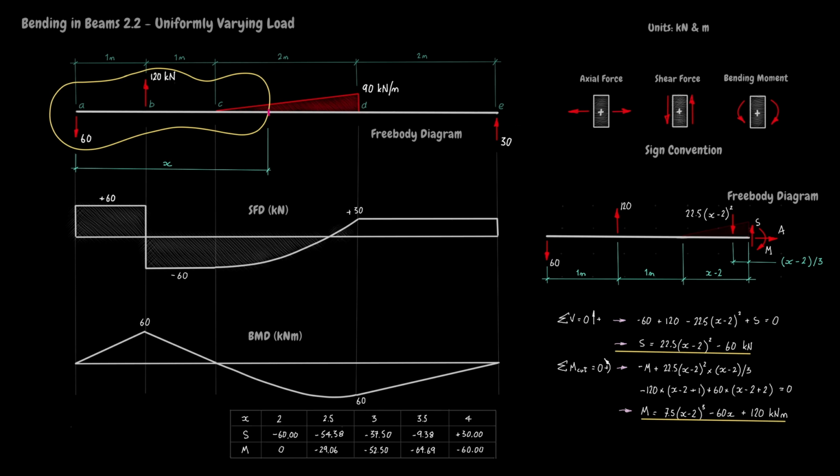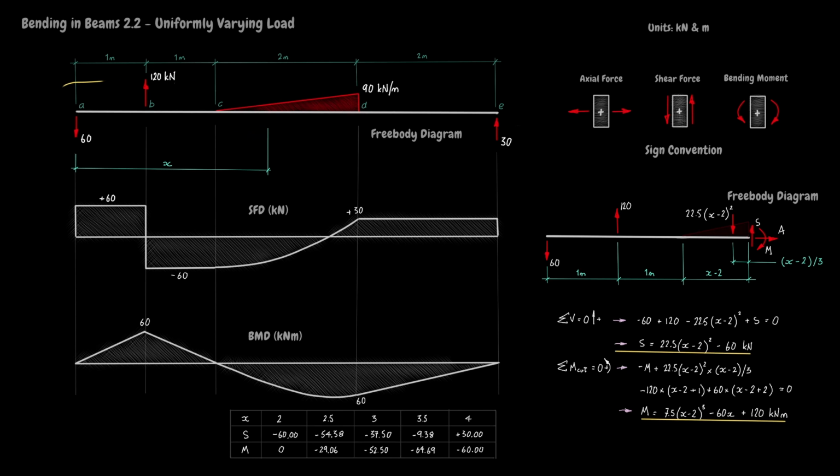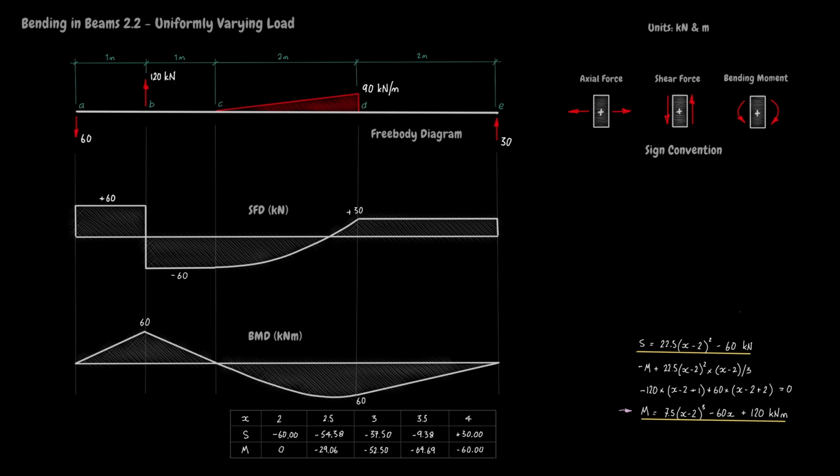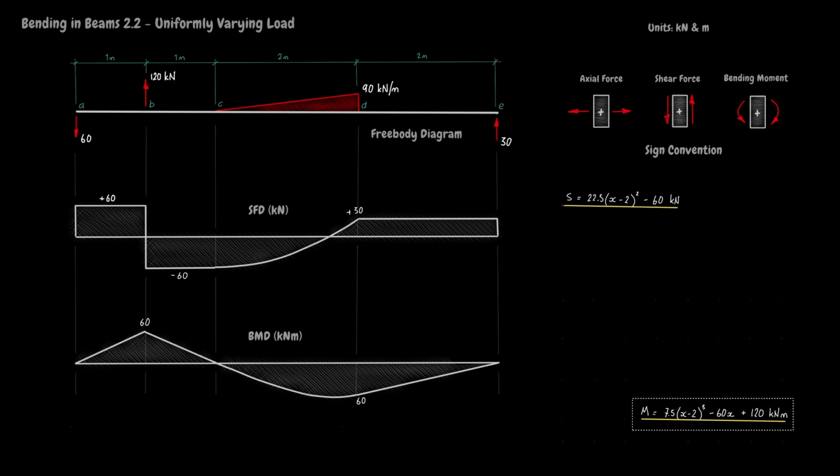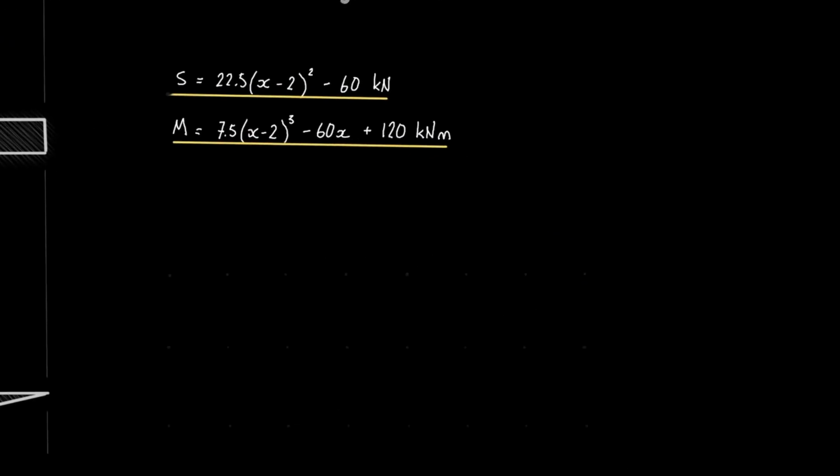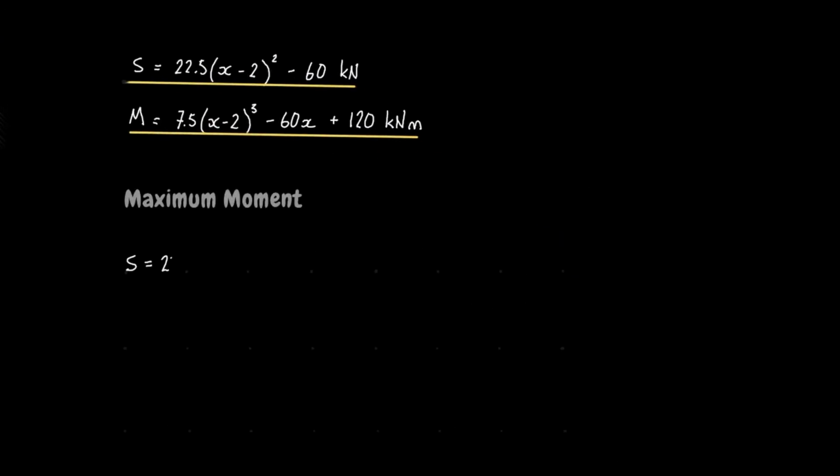It's unlikely that the minus 64.69 kilonewton meters is the maximum sagging moment. So we need to figure out what the maximum moment is. To do that, we will need the expressions for shear and bending, but the rest of the working can be erased to free up screen space. Next, expand and tidy up the expression for shear. The roots of the resulting quadratic equation will give the values of x where the shear is 0.